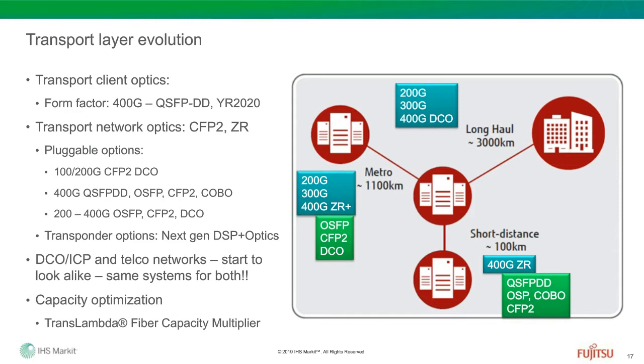For future transponders, DSP innovation will allow a 7-nanometer design with much higher baud rates of beyond 100 gig, possibly offering 1 terabit plus rates per carrier. And DSP would require new technologies to get there. We had to come up with and solve technical challenges to offer 600 gig 64 QAM per carrier in the current generation, and the next generation will require fixing much more challenges going forward.